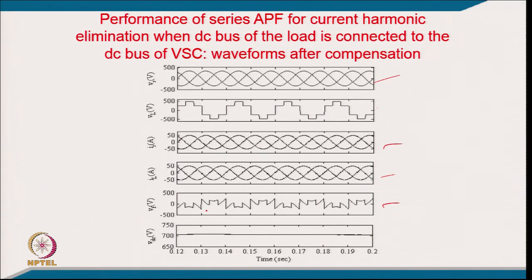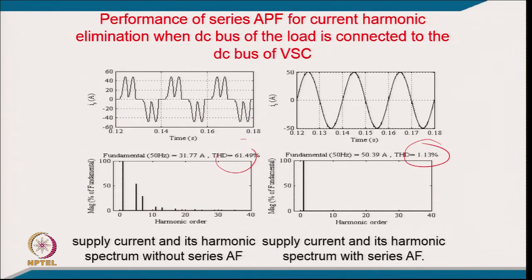So, it is much lower, the current is the same as the load current, and that peaky current is also reduced, as you can see. Here this current was touching even more than 50, but here it is not touching more than 50, and it is virtually a sine wave. Here you will find the crest factor quite high also. So, we will stop here.